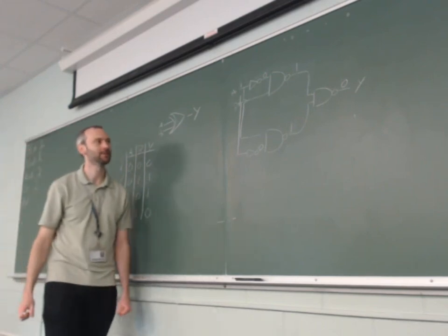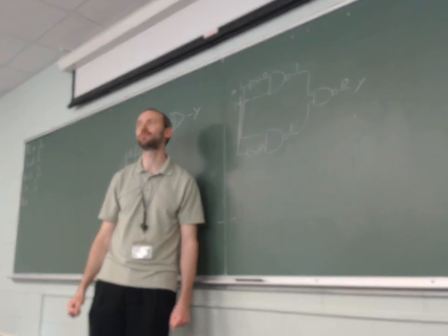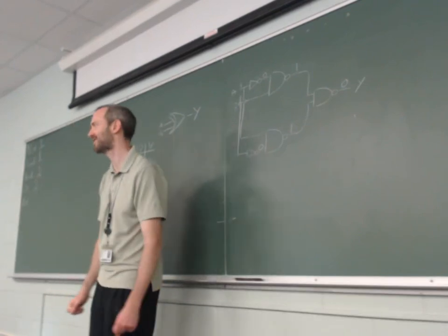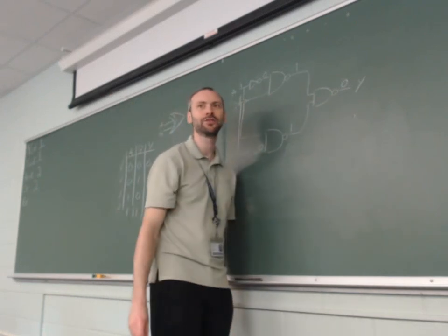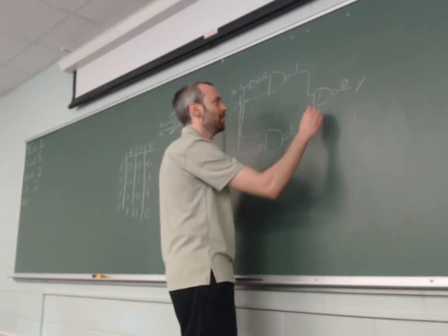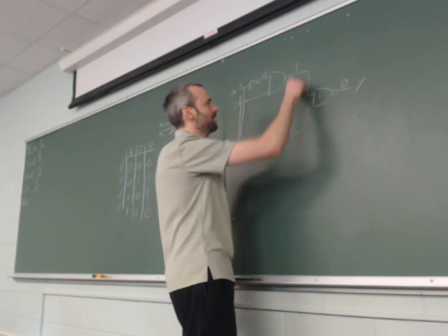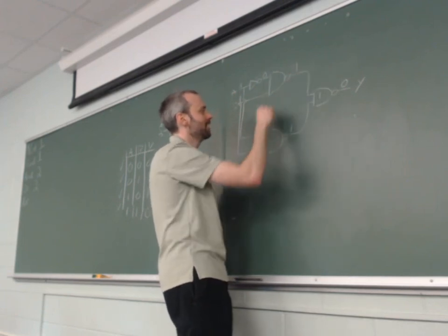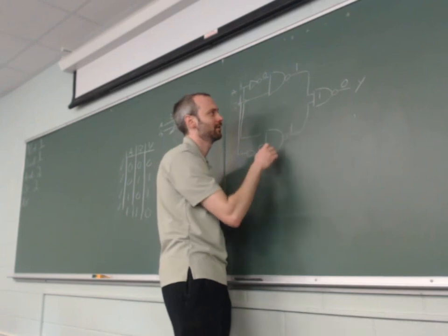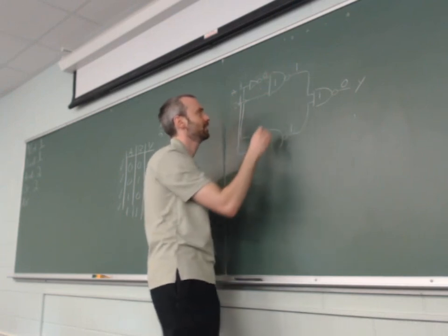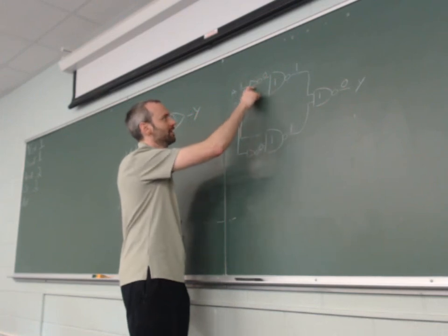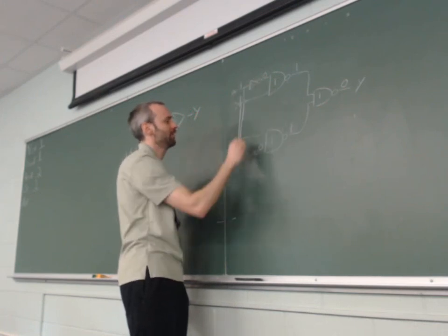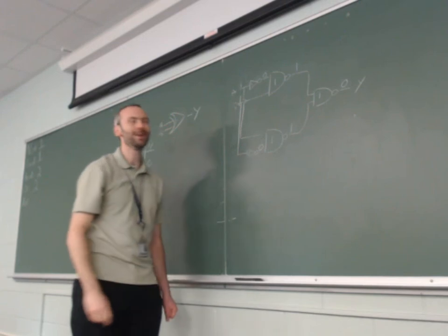All right. Sometimes it helps to look at this backwards, especially since there's only one output. How long does this thing take to saturate? 1. But it's relying on 2 inputs, right? Well, we got this NAND and that NAND. How long do these take? 1 and 1. What are these relying on? Well, these are inverters, so this inverter is still 1 and that inverter is still 1.